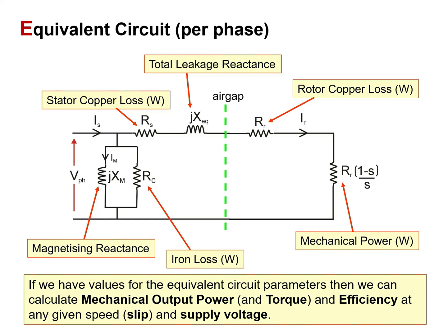However, the difference is that the presence of the air gap makes the magnetizing current have a significant effect and it cannot be ignored. However, the core loss resistance may be removed from the equivalent circuit and its effect accounted for by including the core losses in our calculations. So how can that be done? This is done by referring the rotor circuit to the input terminal.